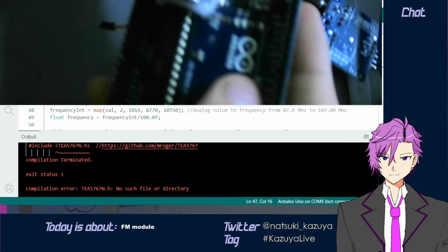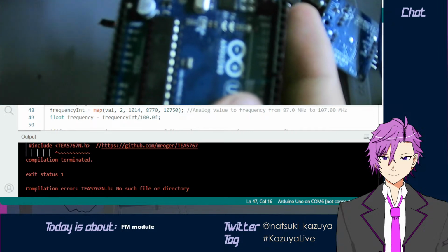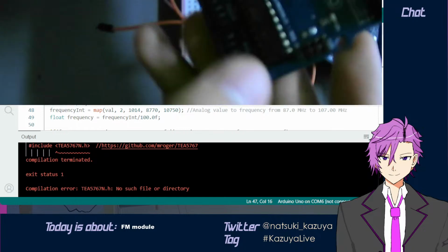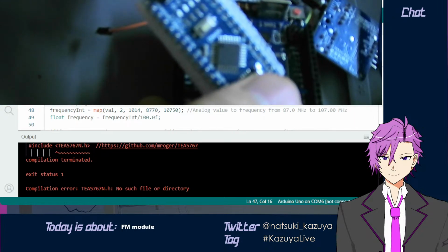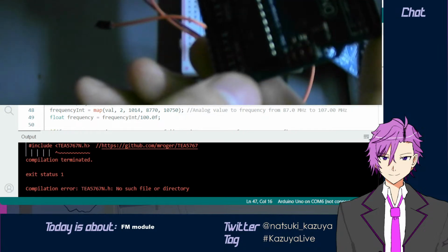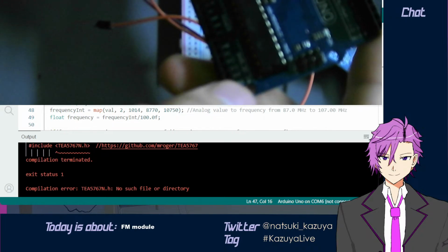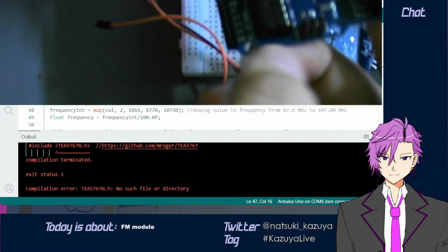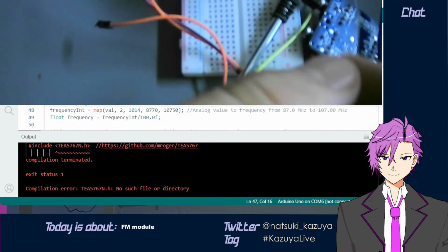I think there's the Arduino Mega, but the Arduino Mega is much better than these two babies. If you want to use this, it's definitely recommended to use the Arduino Nano. So I'll just use the Arduino Uno. If you remember, the A4 pin and A5 pin are the pins for the SDA and SCL. I think A5 is the SCL and A4 is the SDA.